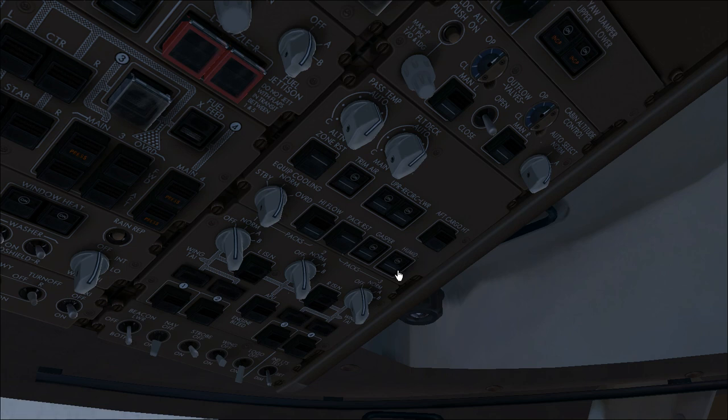One indication for the humidifier, you will probably notice if you've flown a lot of aircraft that humidifiers are not common in the aircraft. This is because the air exiting the air cycle machine, so the pack itself, is very dry. The air outside the aircraft at flight level 400 probably has a relative humidity of 2% to 3% or something like that.